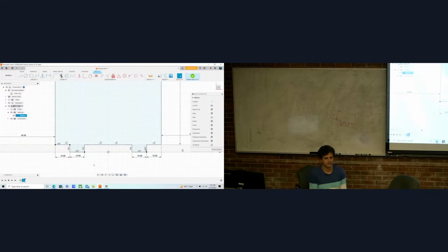And you just dimension it from the outer edge. So are we fully constrained up here? Is our sketch good? Yes, and you know that because we have a lock up here. We already have the distance, so now you want the distance from the outer edge, this wall to here, right? And you can just take that and move the wall. Exact same thing on the other side.